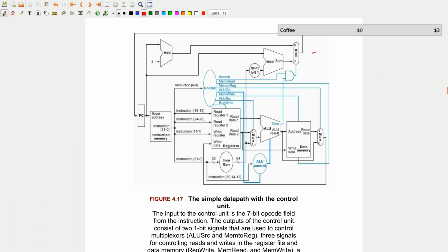So we'll do, say, 3 minus 3. We'll get 0. Generally, when we calculate something like 0, it sets a flag in the ALU. That's what the 0 flag is. So we're just going to check if it's equal and if it's a branch instruction. We know it's a branch instruction from the opcode from the instruction. And so that's what we're going to use for this multiplexer.